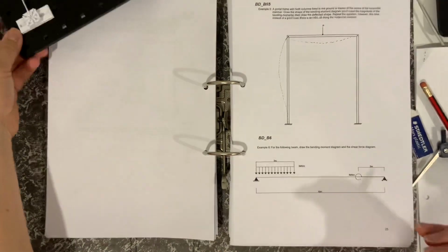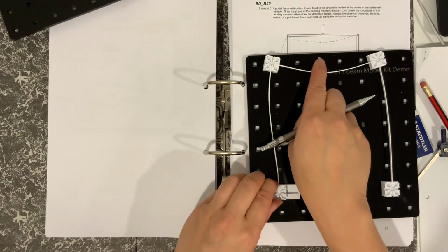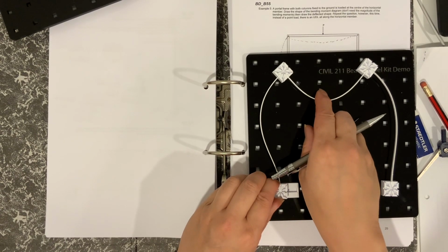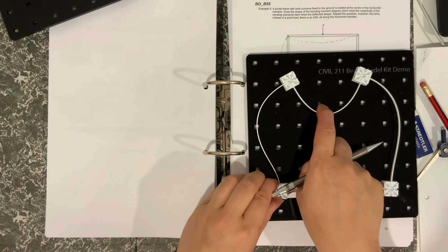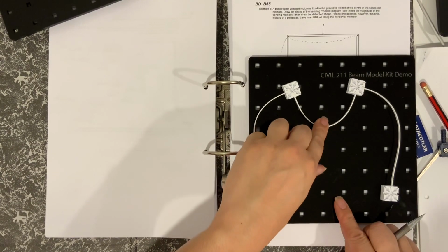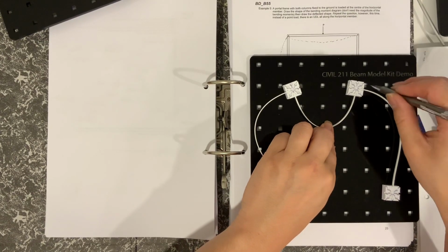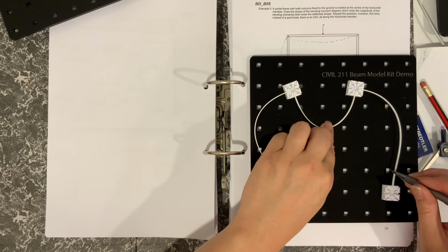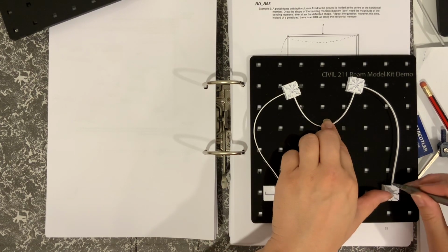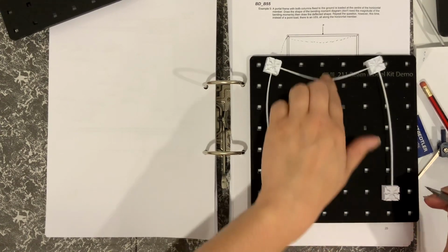So I'll keep my finger here so this end doesn't move, and concentrate on the bottom of the column there. I'll put more load on, and with an exaggerated load on, you can probably see that side is the tension side. So it's still coming out at 90 degrees, but you can see that that side there is in tension.